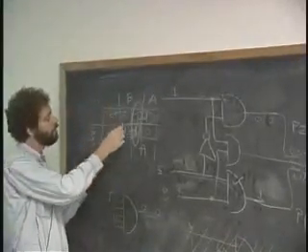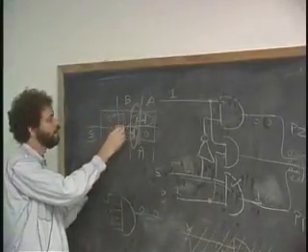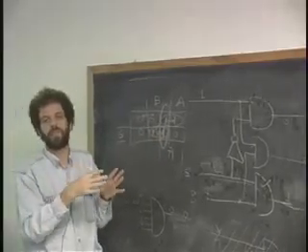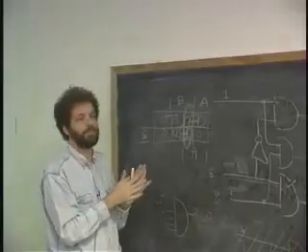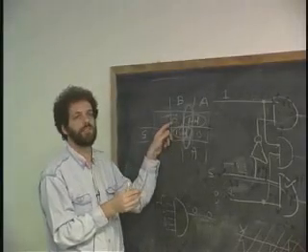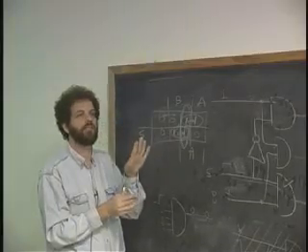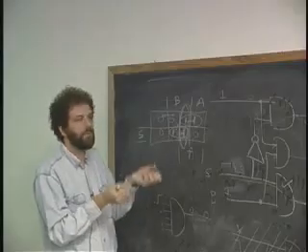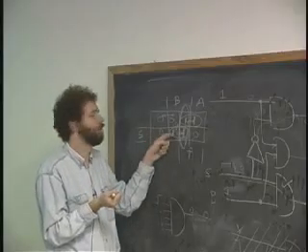Now, in terms of what happens when you go 1 to 0 and 0 to 1, we're not going to talk about that. That may, in fact, glitch all over the place. But we won't worry about that right now. What may glitch? If you do 0 to 1 or 1 to 0. Let's not talk about it right now, because what it actually involves is the question of how many AND terms turn on when you go across one.